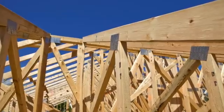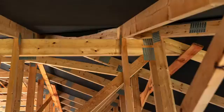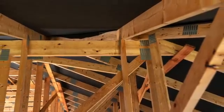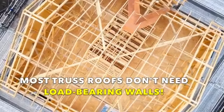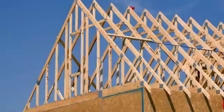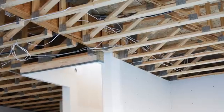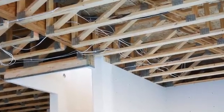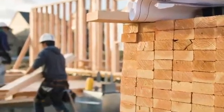They're made of much skinnier, shorter pieces of lumber, pinned together with spiky metal plates. Altogether, they create sort of a web, and that web is very strong. In fact, it's so strong that most truss roofs don't even need load-bearing walls beneath them. They act like a big girder spanning from one outer wall to another. Trusses are also sometimes used for floor systems. They're very strong, they speed up construction, and they cut down on the amount of large dimensional lumber that we used to need to build houses.